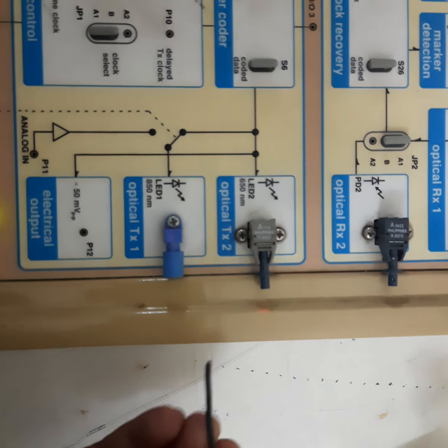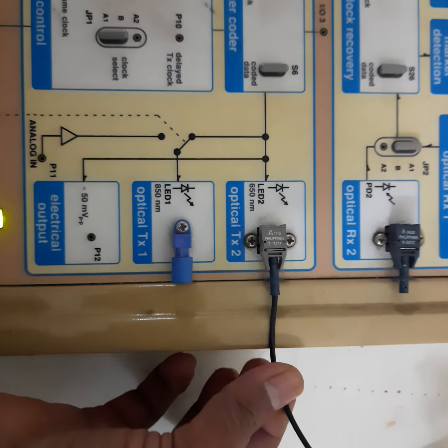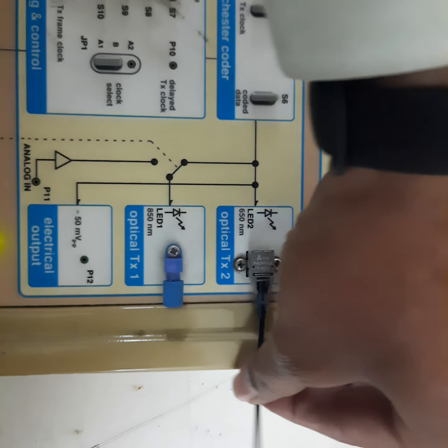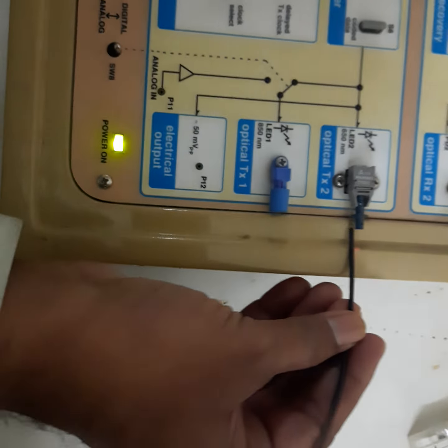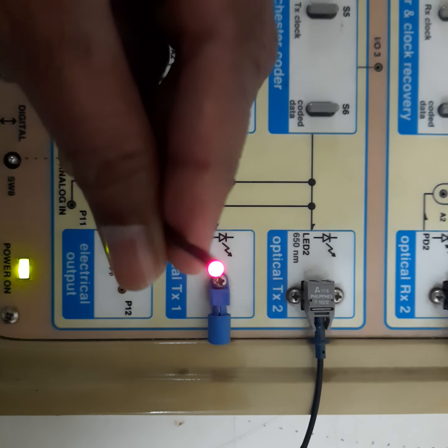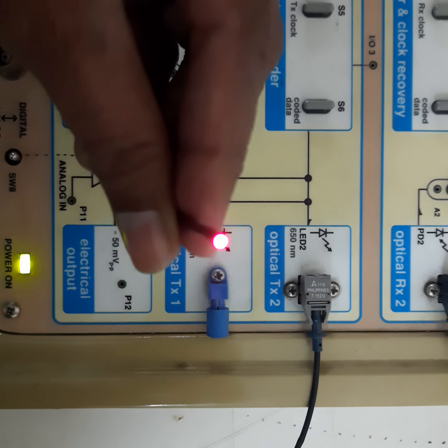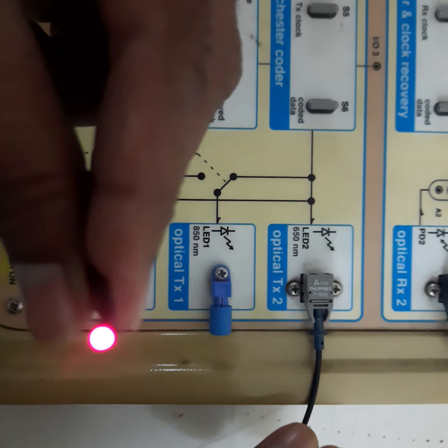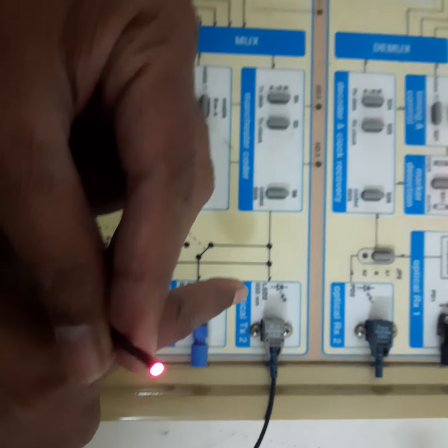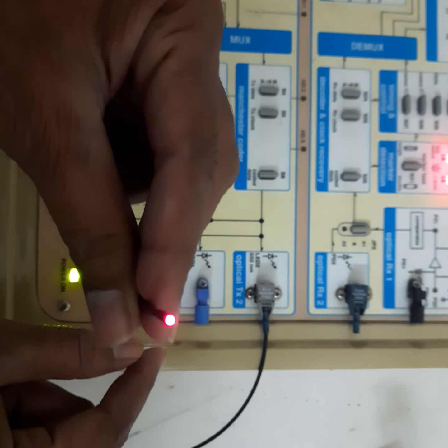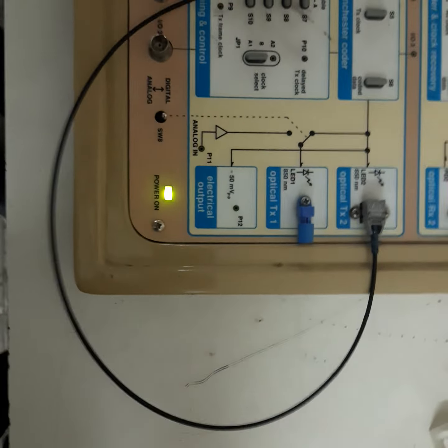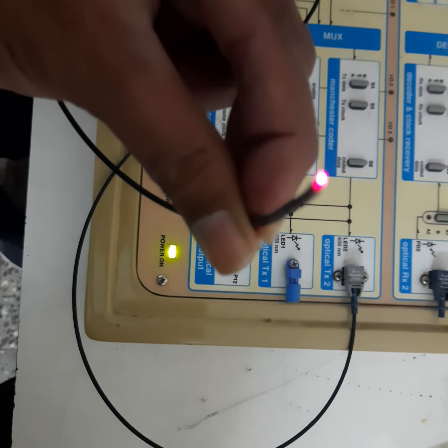Now, this is a fiber. I'm connecting that fiber to one of the optical sources, LED2, having a wavelength of 650 nanometer. So you can see here that from the other end the light comes out, simply because this is a visible source operating at a wavelength of 650 nanometer. So this is an optical transmitter. With the help of the LED, the 650 nanometer light is obtained from the other end of the fiber. This confirms that the source is working and the light is coming out of the fiber. So now we are going to see the simple practical called numerical aperture measurement.